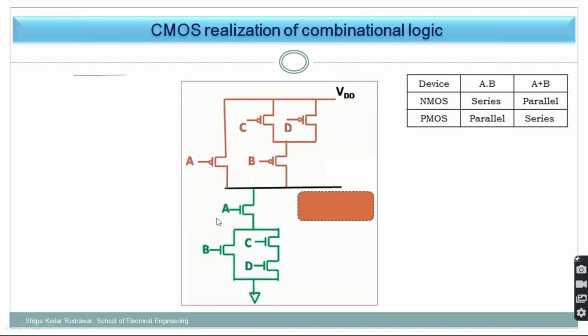Okay, so here A is over here. In series with that I am having this combination. So can I write A, because I am solving for NMOS. Okay, so I am writing this A. Hope I am able to write it properly. So this is A in series with this combination. So series means for NMOS it is the dot multiplication. Now this whole circuitry will be in series.